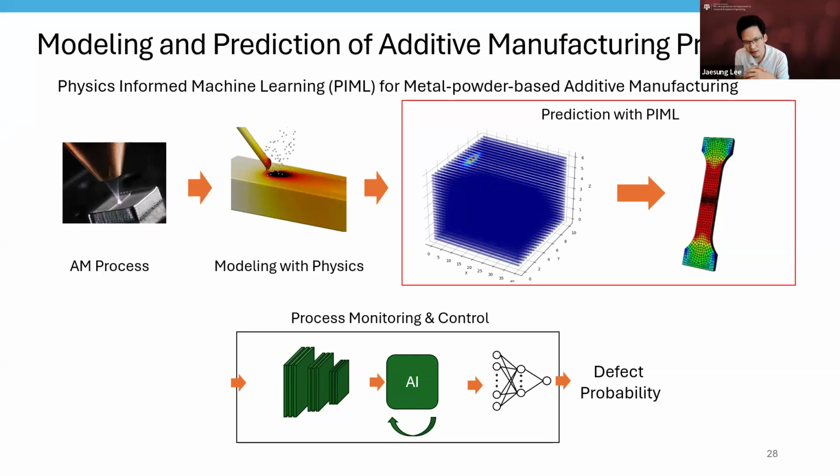For example, this is a metal-based additive manufacturing process. There you have a powder bed, then the laser melts down the metal powder. Once the laser goes from the left to the right, it will melt down the powders, and then it will create some line. You can imagine the commercial 3D printers you can see everywhere, but this version is for metal parts, metal products.